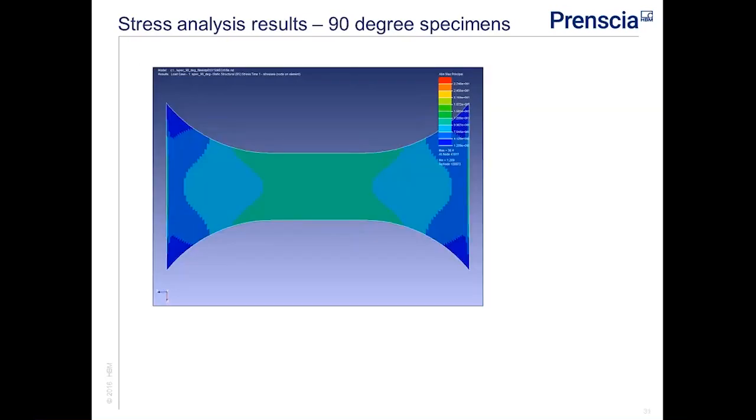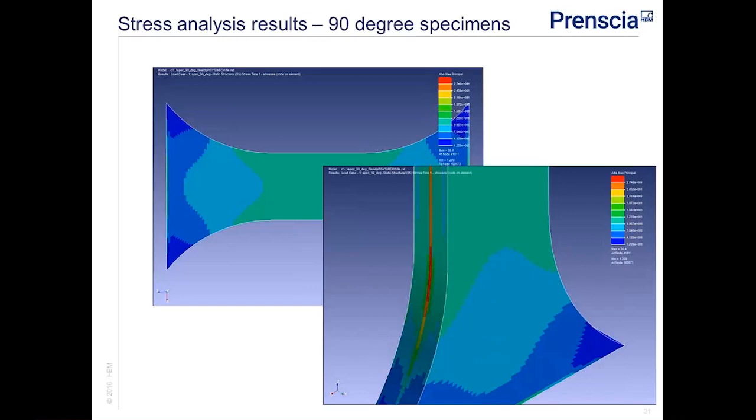And finally, if I look at the 90 degree specimen, that looks like quite a nice stress pattern. But if I look through the thickness, you can see the middle lights up. This is because in the 90 degree specimen, the strongest alignment of fibres is that very thin layer in the core. So I think you can see from these simple analyses that the mechanical behaviour of this coupon cannot be properly understood if we only plot, for example, net section stress against life or net section stress against strain.